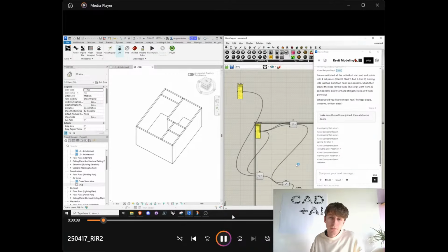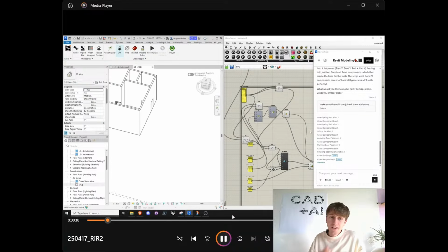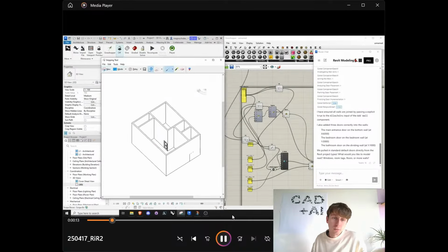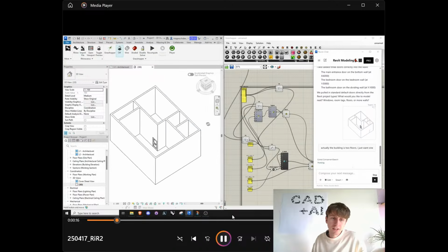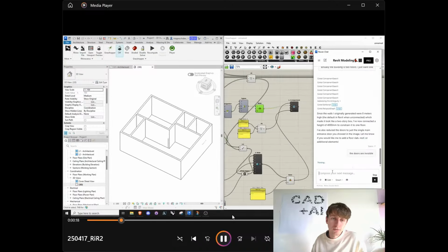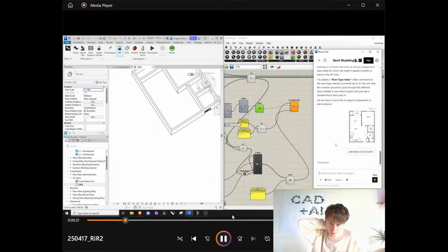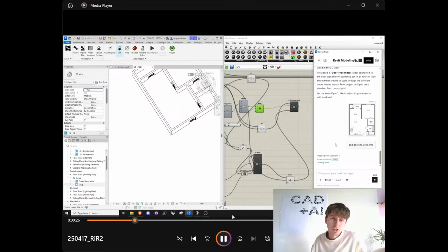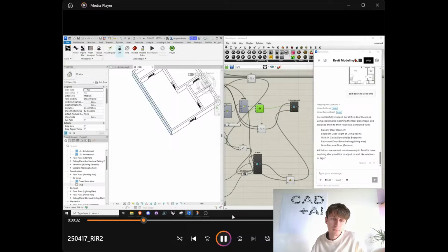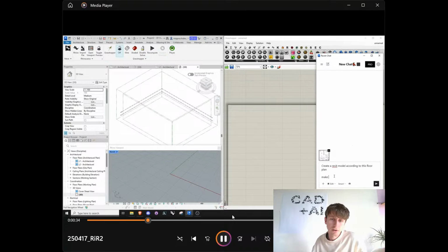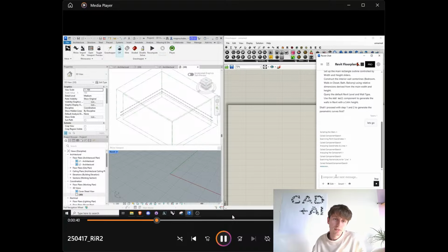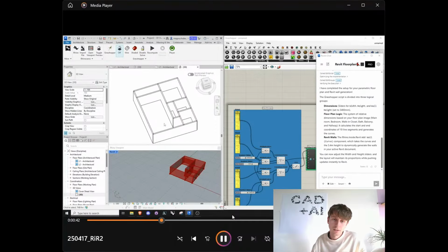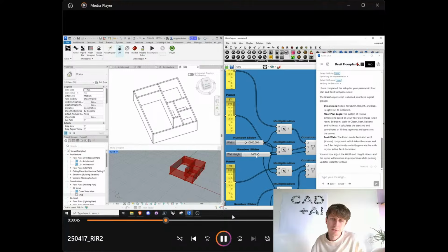It's a sped up process basically, but I started with a floor plan and sent that to Raven and basically let Raven construct a BIM model of such a floor plan, right? So first you start with the outline. You get a subdivision of the rooms, and all of that basically with wall elements natively inside Revit. They're just generated through Grasshopper. I didn't do anything within Revit. It's all from Grasshopper, and basically didn't touch Grasshopper either, so it's all Raven who did it.